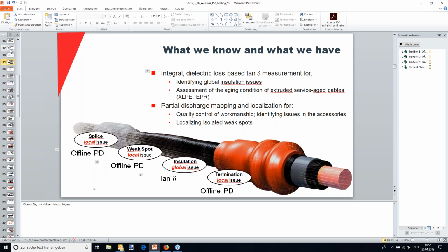While on the other side, offline testing is not really for monitoring. The asset has to be de-energized in a scheduled outage, and then you have full control over all the parameters of the test, and then you can really find out the condition. So that is the big difference. The one is really a substation monitoring tool. The other one, offline PD testing, is the cable tool. As I said, different animals. I hope that answers that question.